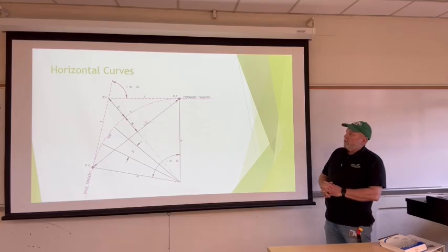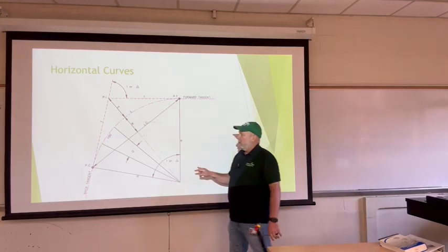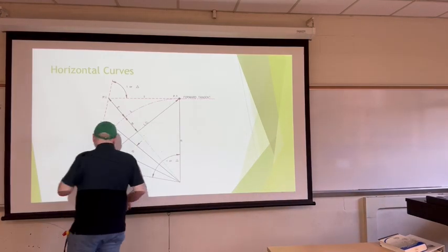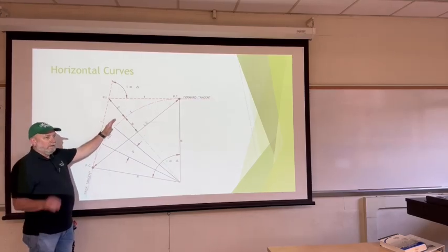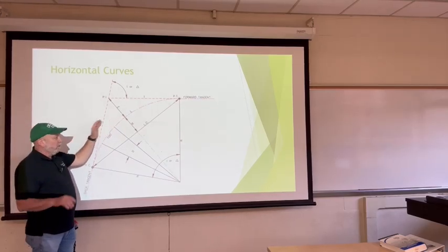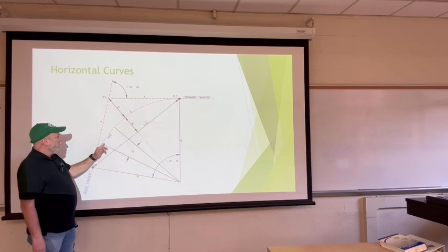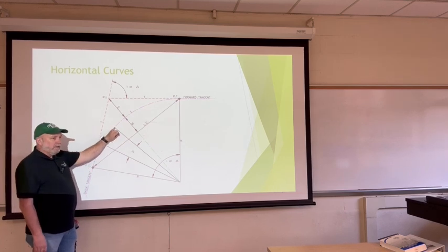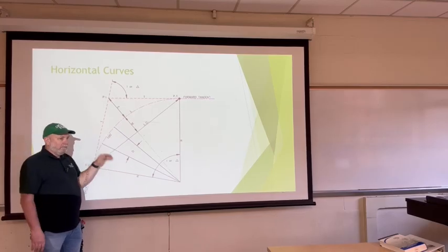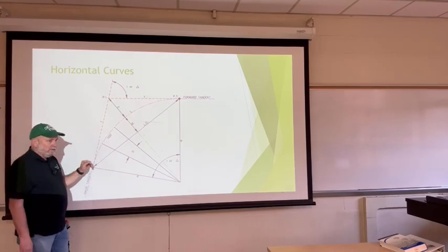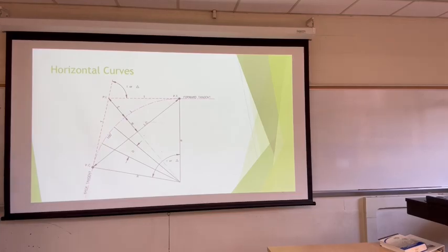When you're talking about the horizontal curve, like your degree of curve here, this is how much angle is subtended by 100 feet of arc length. That's the road. The railroad would be a chord distance there, and that's 100 feet. So that does change slightly depending on how tight your radius is. That's probably the biggest difference as far as horizontal curves and railroads versus right-of-ways.